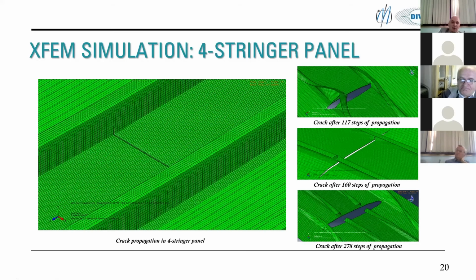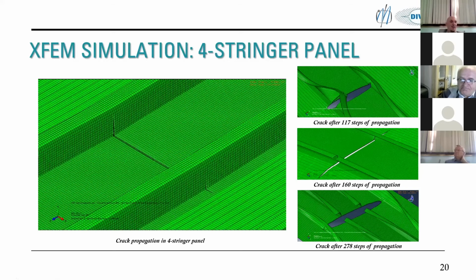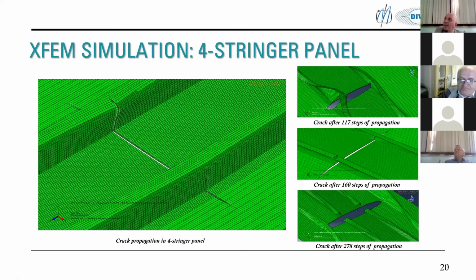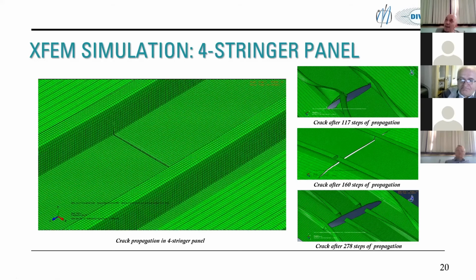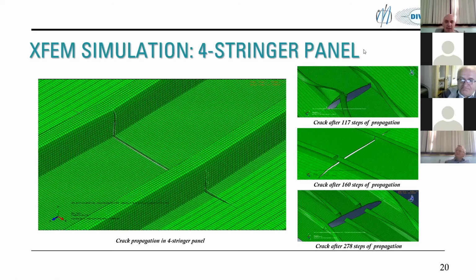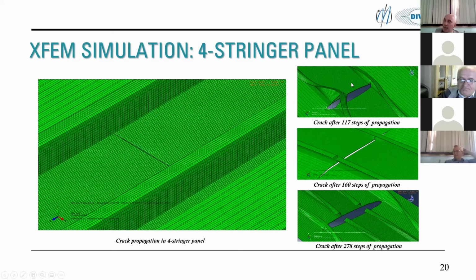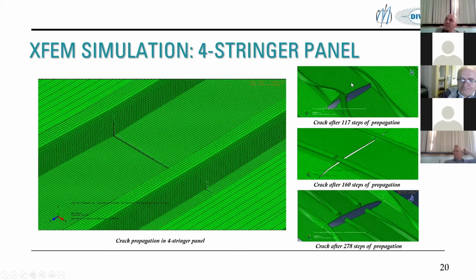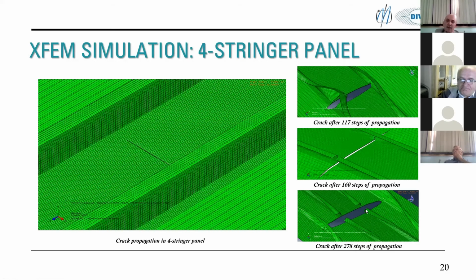This image on the screen is correct, but here on the wall it's not. So, in order to analyze the influence of the mesh size on the number of cycles, we made 3 different models. One model with a very small mesh, 1 millimeter average size. The second was 2 millimeters, and finally 4 millimeters.